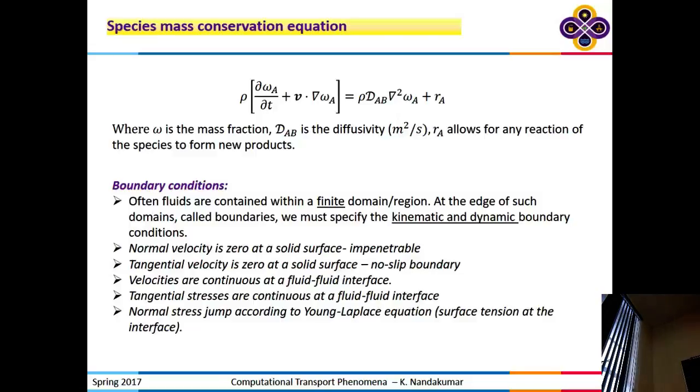And the intuition tells us that if there is a streamline like this, right, and that applies a tangential stress, so there should be a motion like that. And inside the streamlines may be like this. Okay? So there is no slip still, but what it says is both the fluids are moving at the same velocity. The velocity is not zero anymore, like as in a fixed wall.